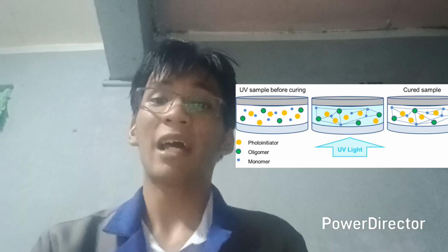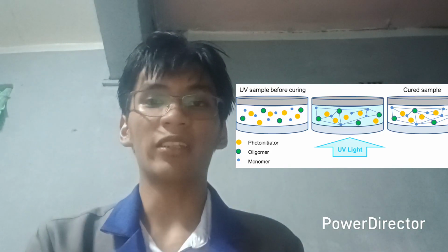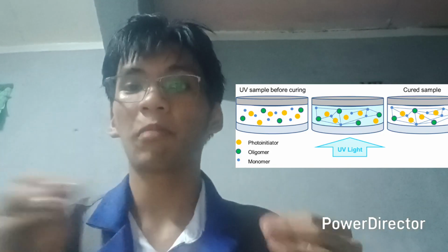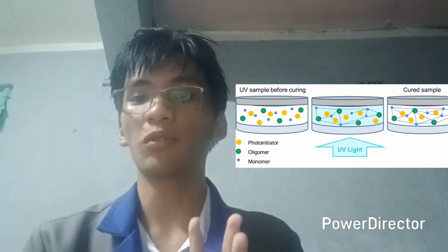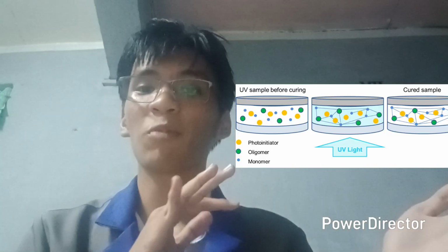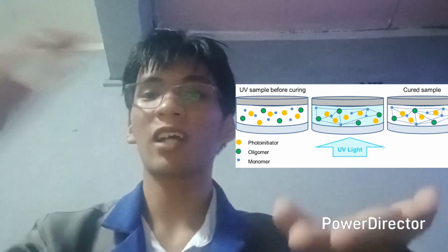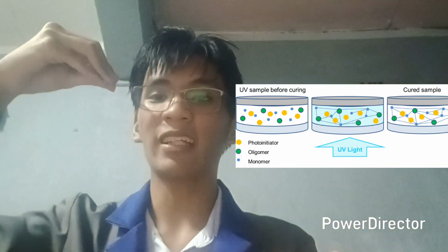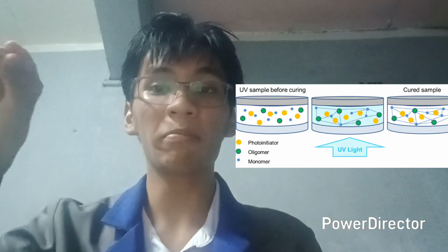Secondly, curing and hardening of the desired object. Different types of processes in 3D printing involve different types of chemicals and chemical processes, as will be discussed later. For example though, photoinitiators are a specific type of chemical present in the substance that will be used in a specific type of process. This process involves a substance coming into contact with the UV light in the machine of the 3D printer.